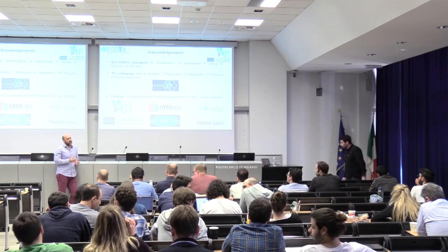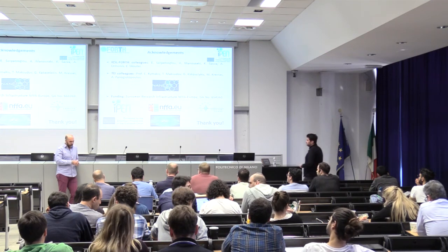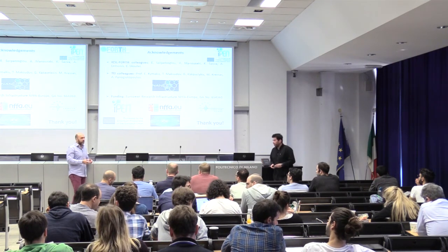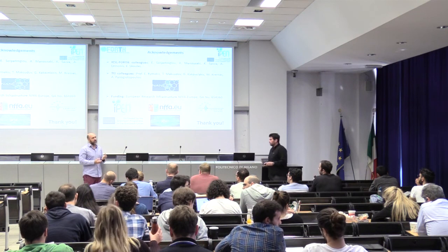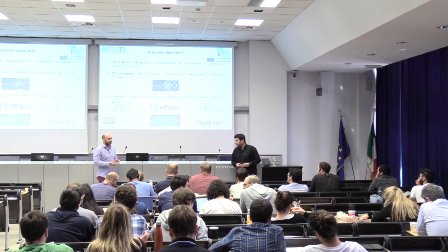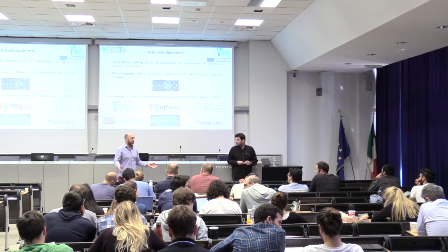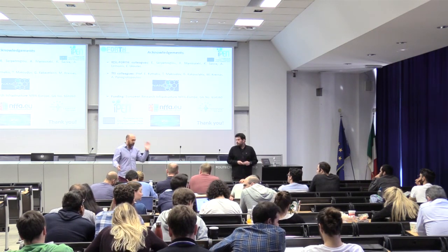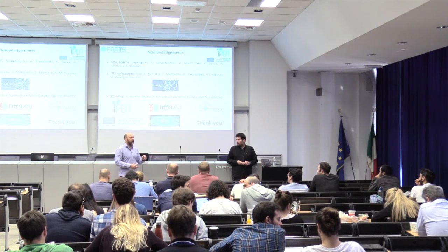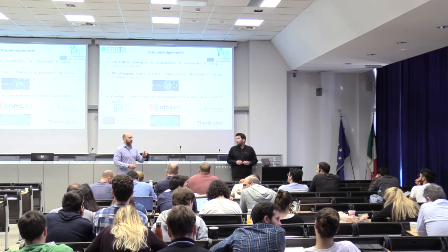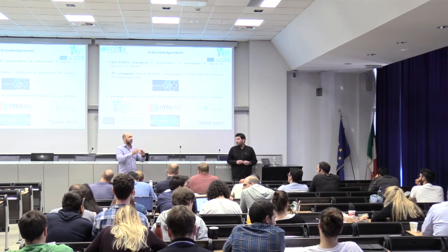The problem with the perovskite, as Yannis mentioned in his talk, is that the efficiencies reported are for small cells, like 0.5 millimeters. When we move to the modules, the technology changes a lot, and the efficiencies drop to less than 10%. So now they are trying to combine silicon with the perovskite in order to keep the high efficiency of the small cells in the modules.